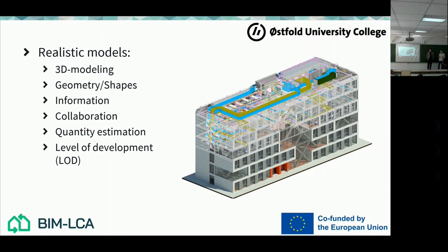So if you're missing an object completely, or missing another geometry of an object, for instance, you have a foundation that is 1 meter by 1 meter, and you need a foundation that is 1.5, you just make a copy and make another type. And then you can expand your library, so the library of the content will increase as you use it.